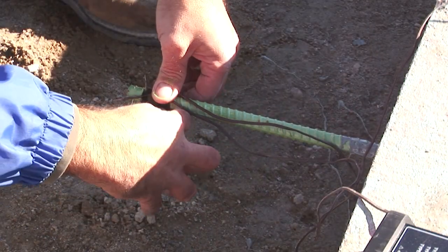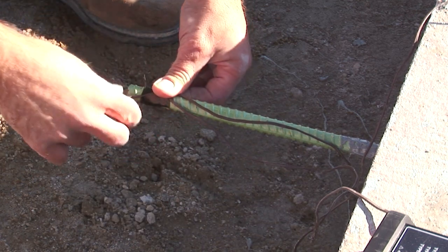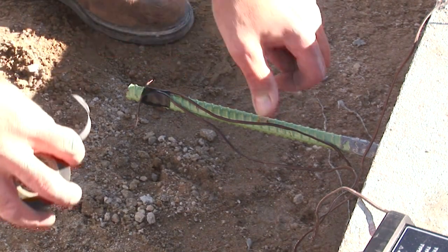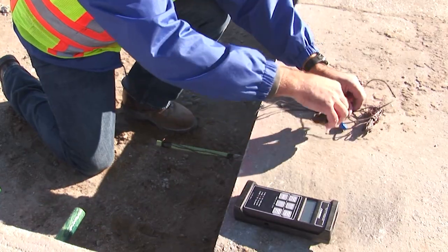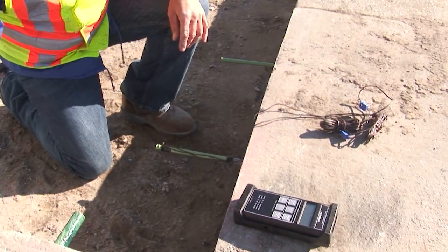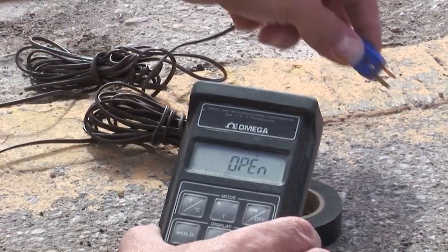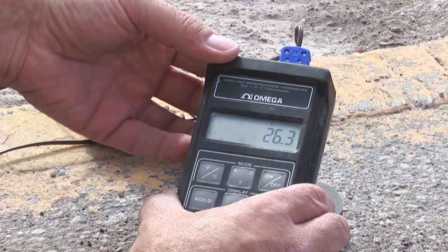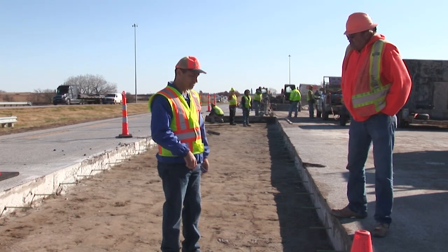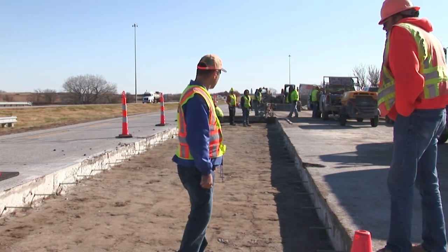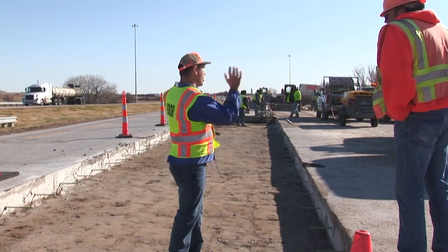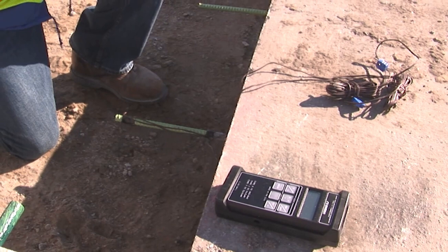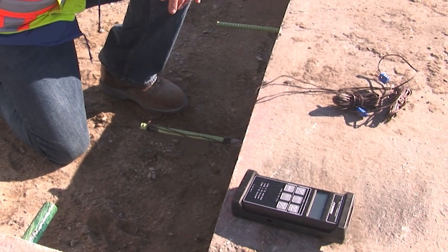The most common installation method is by attaching the thermocouple wires by tying or taping them to an existing tie bar or dowel bar in the removal area. Run the wires onto the adjacent slab of the removal area. Test the wires for conductivity by taking a temperature reading with the monitoring device. Once the wires have been tested, it is recommended to take measures to protect the wires and connectors from being disturbed. This may be accomplished in several ways, not limited to the example shown here.